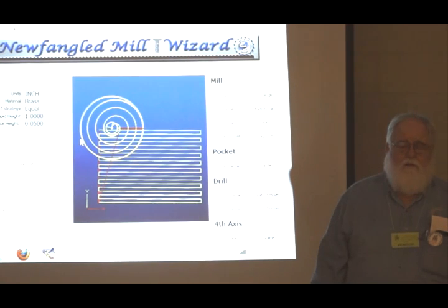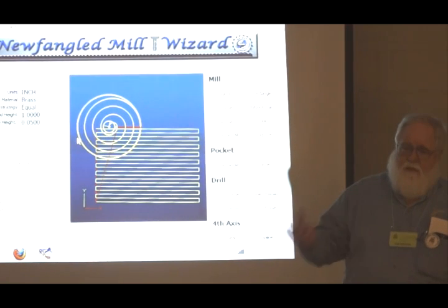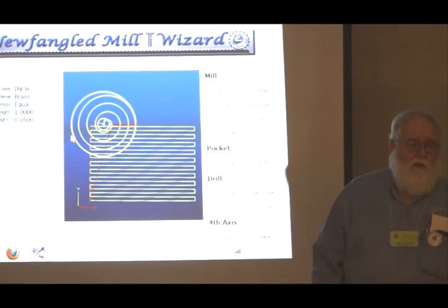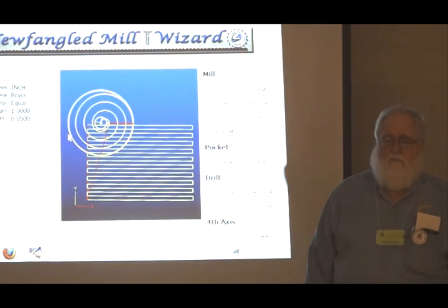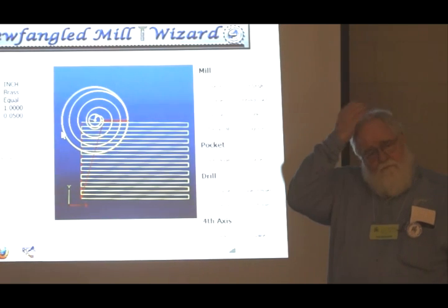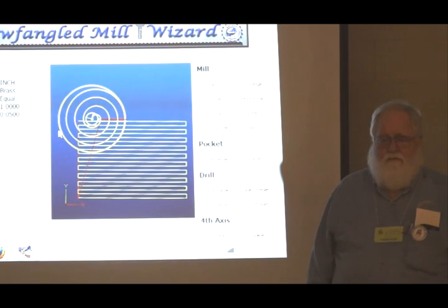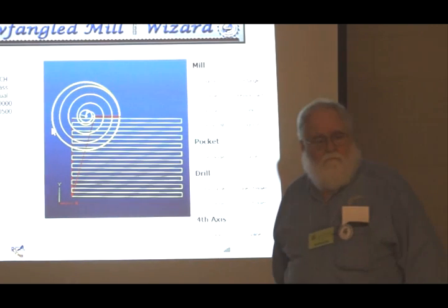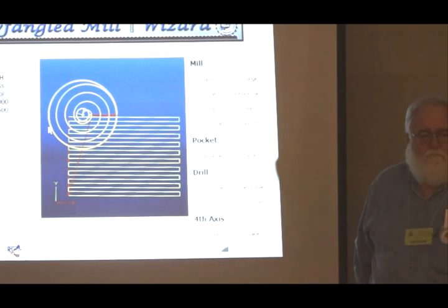As I said before, you could do 2 entries and make the second a full depth cut, okay? Make the finish amount be 0, so it doesn't do it. But that was just, my view is it's easier to do 2 steps in the operation and get your finish. Suppose you wanted to do a disc, make a 5-inch disc.